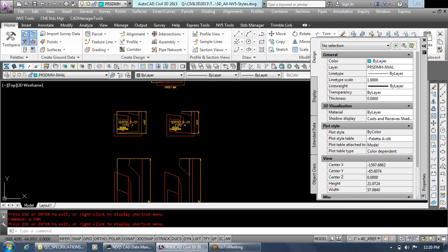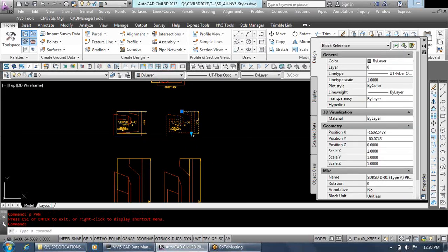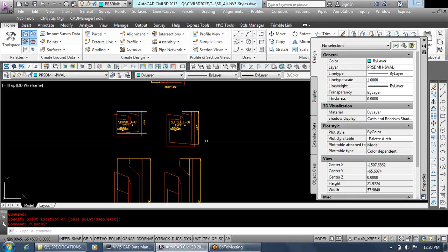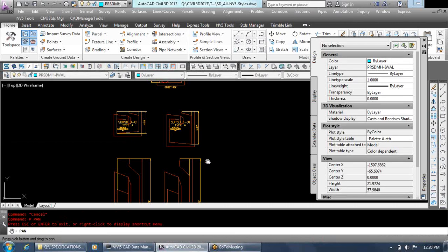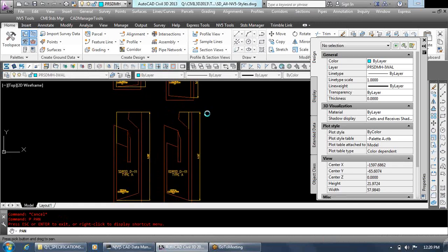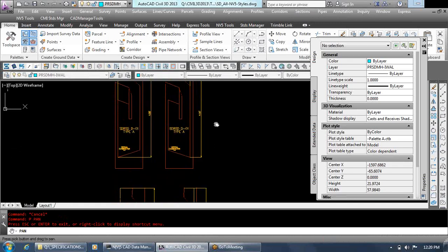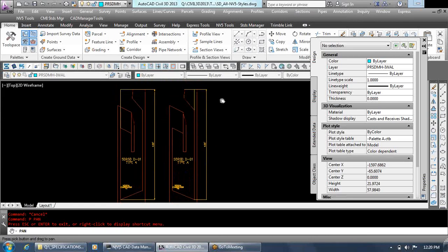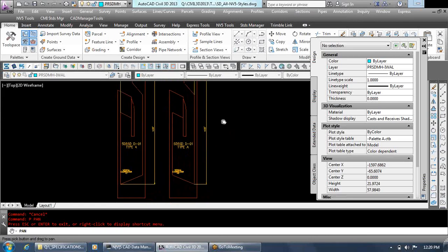These are dynamic blocks as well, with the depth of catch basin being the dimension in dynamic. So you have it as drawn 1:1, and then you also have it at the two most commonly used vertical exaggerations, a 4 exaggeration and a 5 exaggeration. And both of those dynamic variables work as expected.